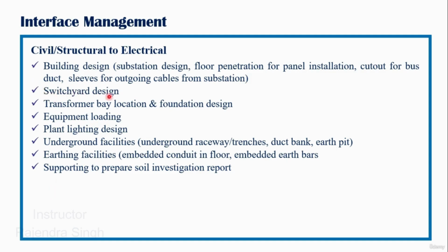For the switchyard design, the structure design is done by civil. So civil has to provide us the input so as to enable the switchyard design for the outdoor electrical equipment. Transformer bay location and foundation design. Equipment loading. Plant lighting design.